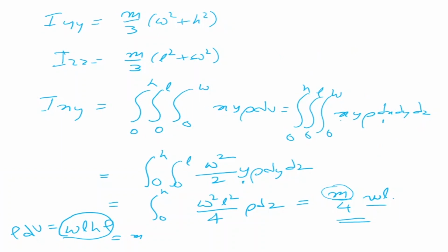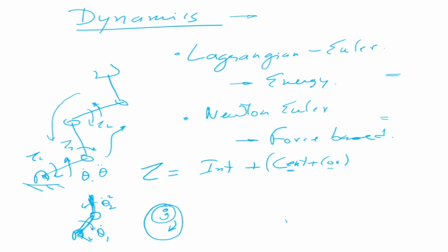So what we were looking at is the forces that the torque is made up of. What kind of forces? Inertia forces. Inertia is because of acceleration. Then centripetal and Coriolis force, plus there is gravity which is acting. Gravity is always there, pulling the link down. So gravity is acting in that direction.